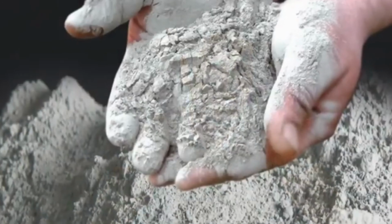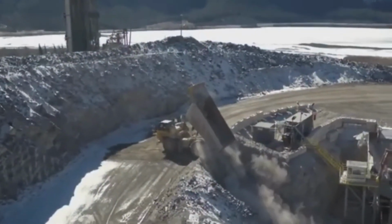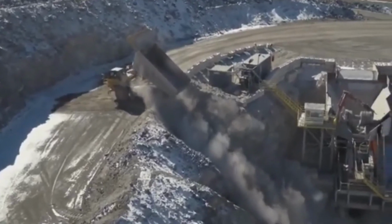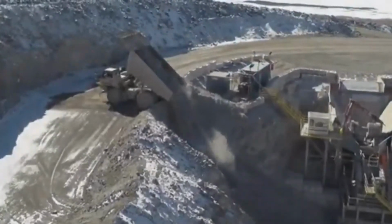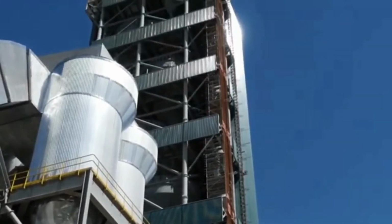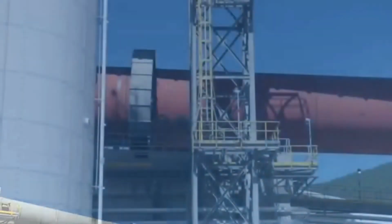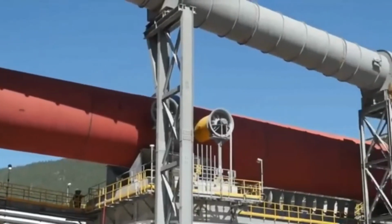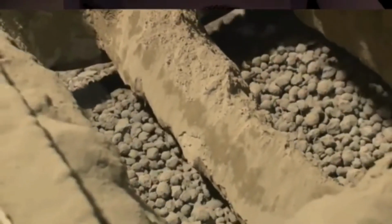Preparing cement. The cement used in concrete is Portland cement. Portland cement is made from a certain kind of limestone that is found in deposits under Earth's surface. The limestone is quarried out of its solid deposit in pieces. Then it is crushed into a fine powder in a crusher. Some shale and clay is also crushed and mixed with the limestone in the right amounts. The mixture of limestone and clay is fed into a rotary kiln and heated at a temperature of 2700 F. During the process, it forms a porous mass called clinker. The clinker is taken from the kiln and ground to a powder. Then a small amount of gypsum, much like the lime used in masonry, is added to make the Portland cement.